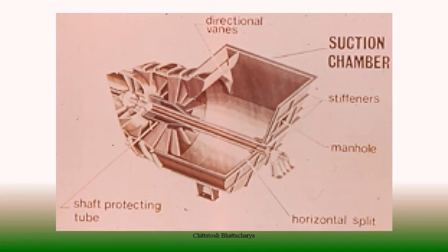That means when the opening of dampers is 70%, the flow is 100%, and when we go for complete closing of the dampers, even then there is a minimum 25 to 30% flow. So control is basically within a range of 30 to 70%. We don't have beyond that.